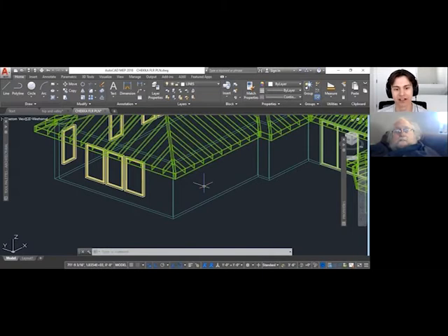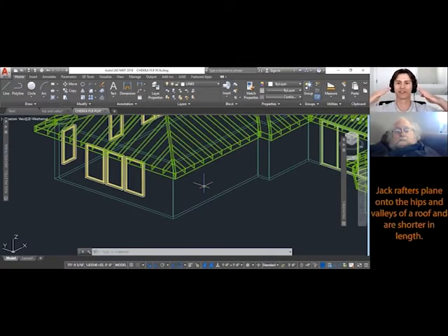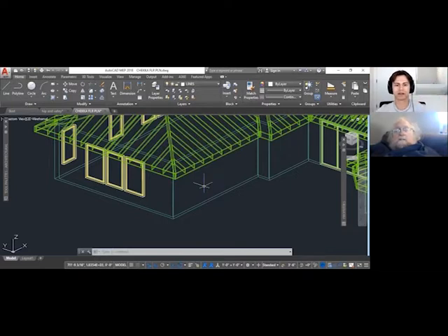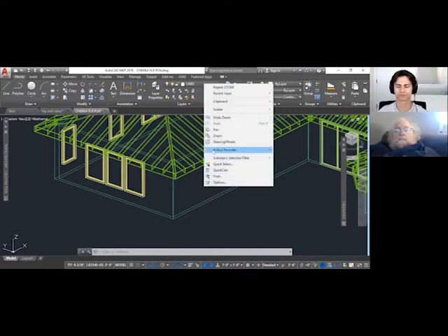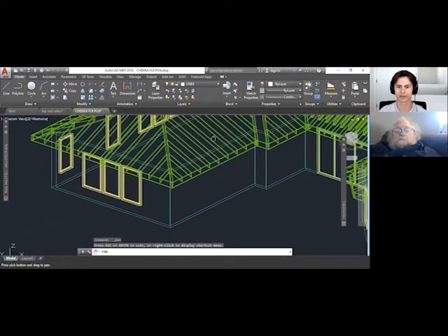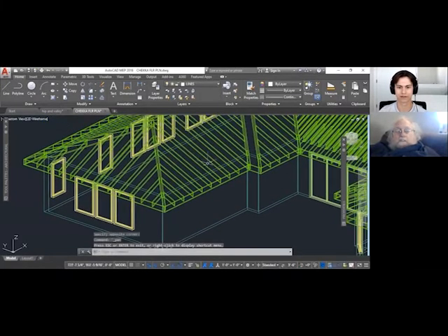A jack set, you're talking about the jack rafters and how to calculate the length of the cut going up. Right. What I want to do is show how I approach it. What you have here is a hip rafter and a bunch of jacks, and each jack gets longer as it nails into the hip. So here's how I determine how to cut that.